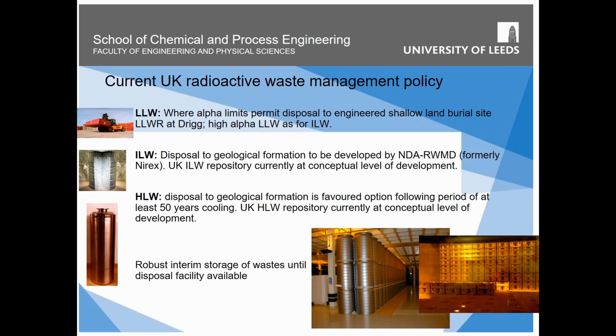Now we decided in the UK that we would dispose of those in a deep repository, and it'll be a co-repository because we'll do it at the same time as HLW. And the reason we've done that is we decided if we're going to build one repository, it's easy enough for us, or better for us economically, to build a single one to take both ILW and HLW.